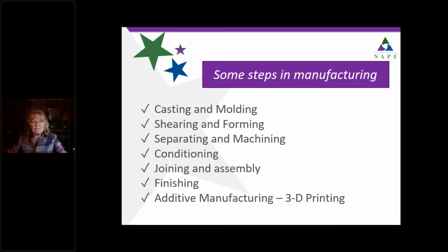Shearing and forming. When dealing with sheet metal, shearing comes into play. Shearing uses cutting blades to make straight cuts into a piece of metal. Another metal shaping process is called forming, which uses compression or another type of stress to move materials into a desired shape. Although forming is often used with metal, it can also be used on other materials, including plastic.